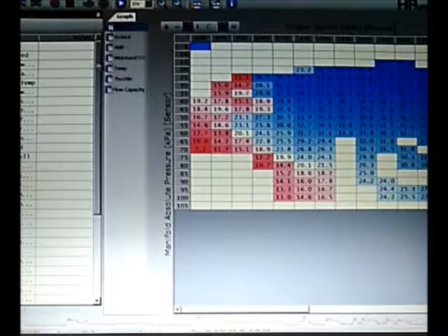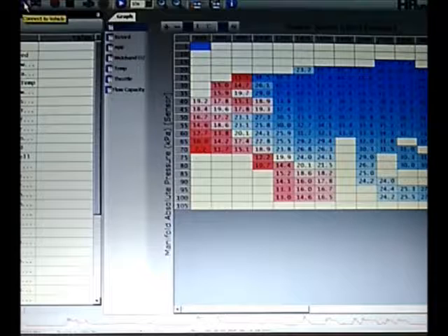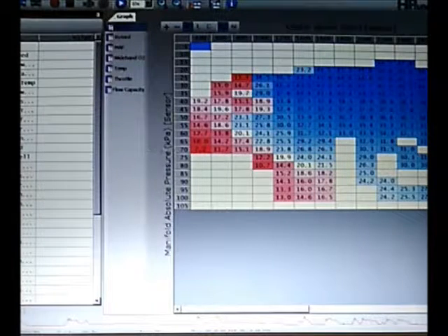In order to test to make sure that you've done everything properly, all you have to do is go up here, connect to vehicle, and when you do that, you won't see a change right away. A window will come up and it'll read the computer and determine all of the supported functions that the car supports, but it won't actually show you anything. So in order for you to see that everything is working, you have to click on the start scanning button up here, the red button, and that will actually start recording the values, and you'll start to see them show up on the table.